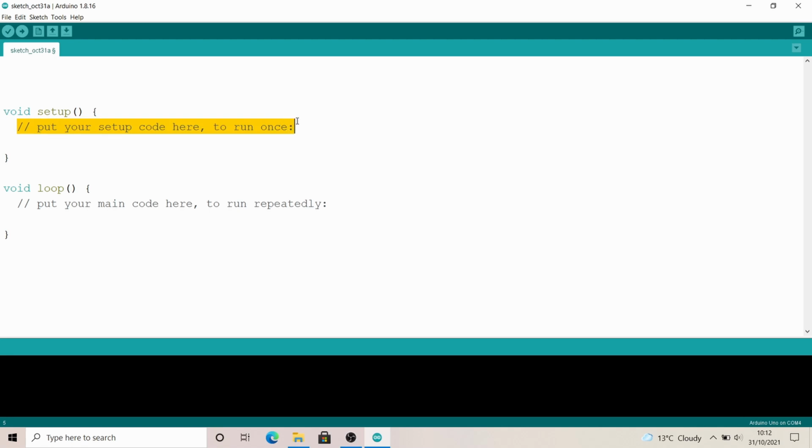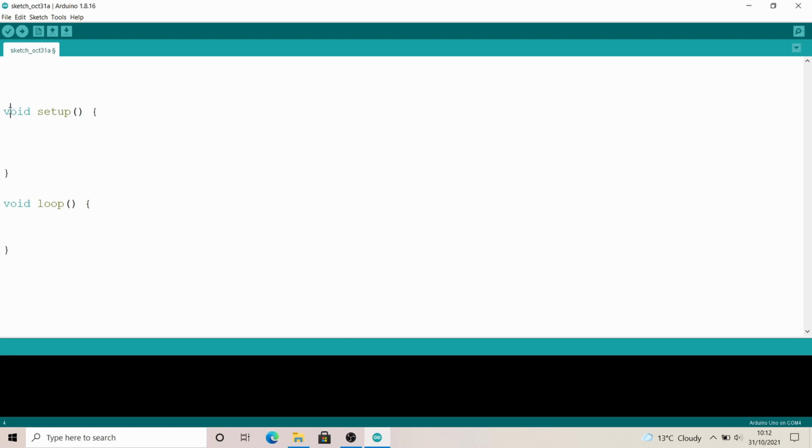Let's open our IDE software. Let's start with our minimum program, minus the two comments. As sending data out from the microcontroller requires physical ports, we will need to set them up in the void setup area of our blank program. We can simply type Serial.begin, with only the S as a capital. This is followed by open bracket 9600 close bracket, like so. Basically we are turning the serial transmit and receive ports on, and this is set to a 9600 bits per second transfer speed.